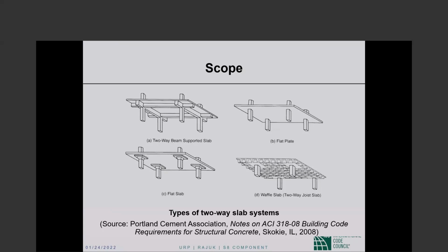Among all the slab systems available to us, the flat plate slab system will give us the shallowest story height, which you translate into a lot of savings in, first of all, cladding, secondly, electrical cables, HVAC ducts, telephone cables, anything that goes up a building. So that makes the flat plate, as I said, the most popular slab system there is in concrete for sure.